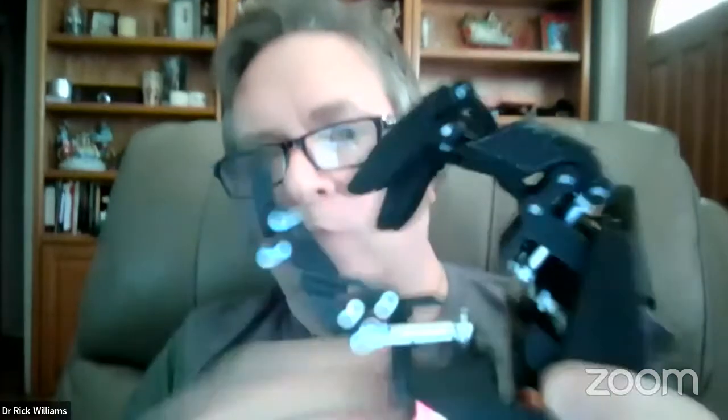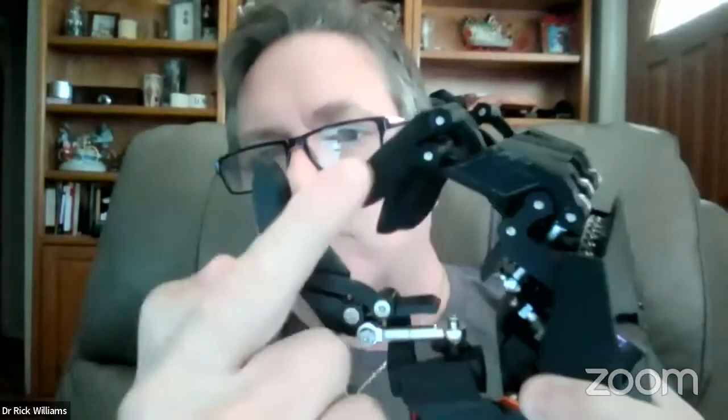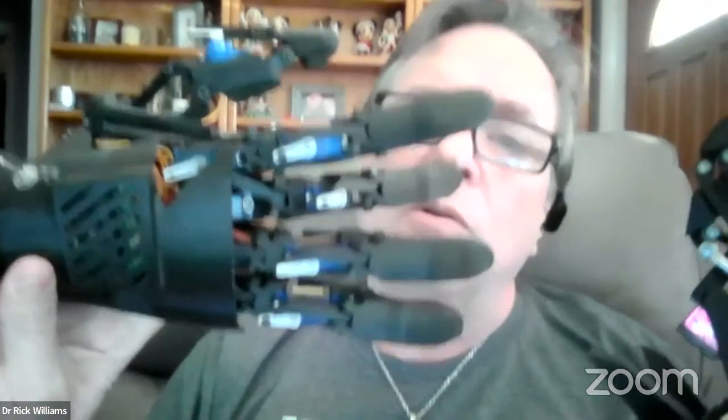However, this one has helicopter parts and only one servo per finger, whereas this one actually has 15 servos, which would be 2 servos per finger, a wrist, multiple for the thumb, and of course the swivels. Now, I have to tell you, these servos take a lot of power. If you're driving 15 servos, you need some amperage, and it's incredibly impractical.